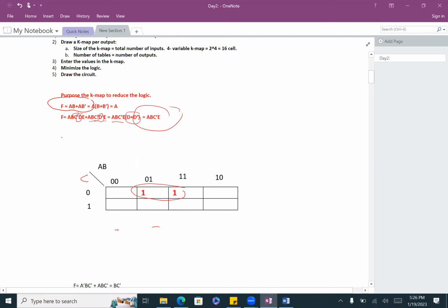Let's see. So out equals, I will look in this direction first. What is the common? 1 and 1, and that's 1 and 1. It represents B, because it's AB and AB here, correct? A changed from 0 to 1, so we ignore it. B is 1 and stays 1. That means it's common. I write it down, and it's B, not B bar, because the value is 1.